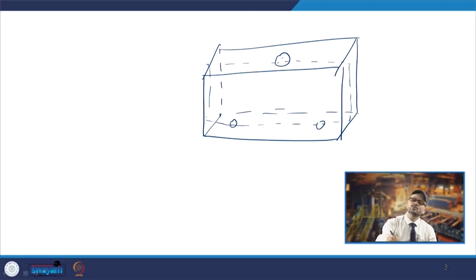So, accordingly your computation time will be 1/2. Again, in such kinds of geometries, you can have a further bifurcation from half, because again this is the mirror geometry of this part. So, you can have the solution only for 1/4 of the domain. So, your computational time normally becomes 1/4 of what you are doing, and that is helpful when you are solving the equations.